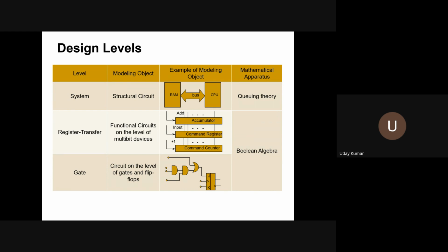Okay, so if you want to customize your chip for better performance, then you would want to increase, for example, the memory density of the RAM. Currently the best memory density of the RAM is like 4 to 5 gigabit per millimeter square. The Apple Bionic processor, I think from a year back, has about 1 centimeter square area.